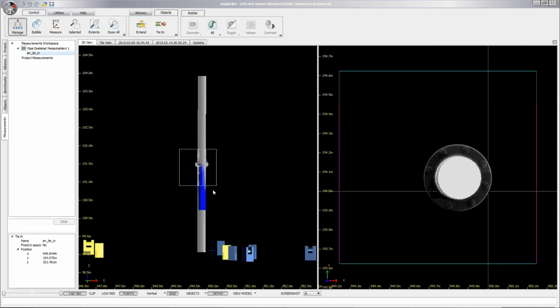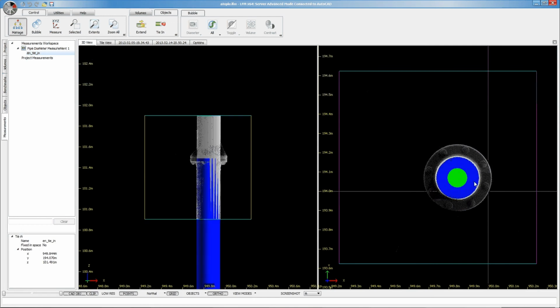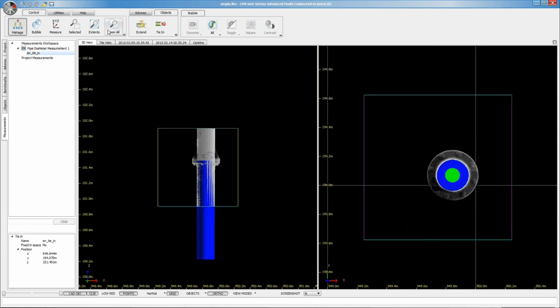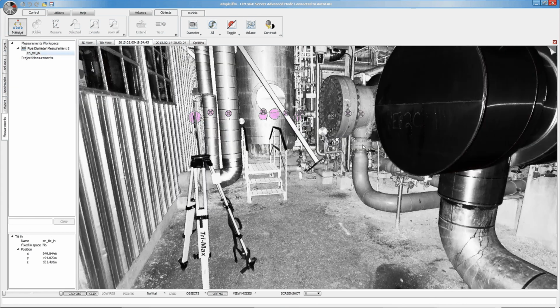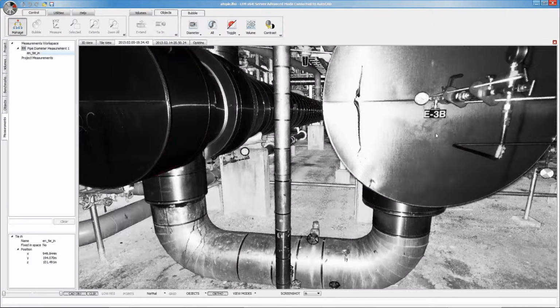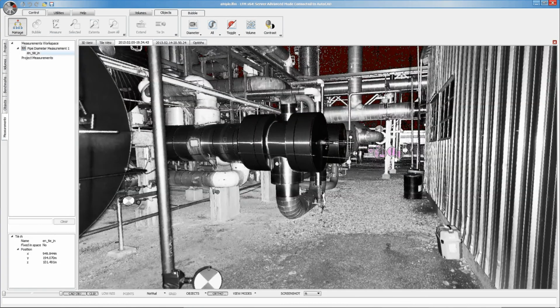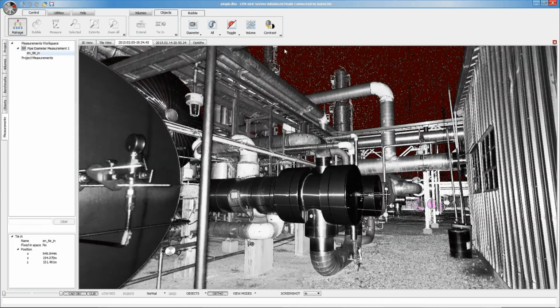And one more thing about this view, this single piece of pipe is representing an entire model of a plant. And obviously if we were looking at this single flange inside of a plant, we wouldn't see it because of all of the CAD objects in the way. But just by going clip, we only see the CAD objects that are inside of our volume. Come back to our model view. If we were interested in anything else that we can see, we can click on it and go directly to it both in our laser data and in our AutoCAD.